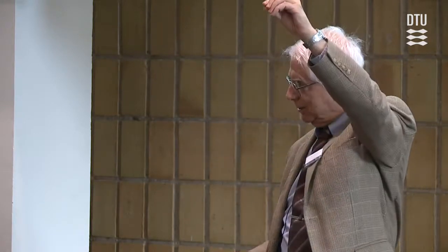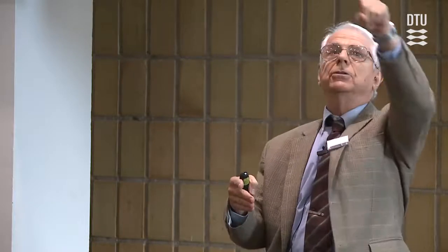Each part fixtures the other part at the neighboring point where they locate each other. And so if the X direction is what we have to control at the assembly level, then we have to go around the chain and see that the X direction is controlled at each of the interfaces around the chain.